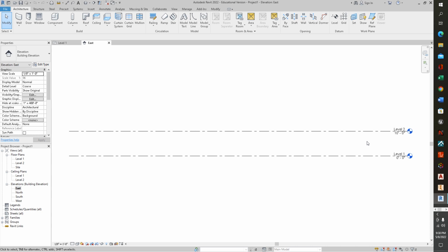The other alternative, of course, is to have actual elevation heights that you could put in here from your sea level and work your way up, and that's totally fine. Then you would at least know if there was some bylaw that was required to work with that would allow you to only build up to such and such a height from the elevation of usually some datum point on your sidewalk or such that the city's surveyors have put in there, then you could work with that and ensure that your building is within those parameters.